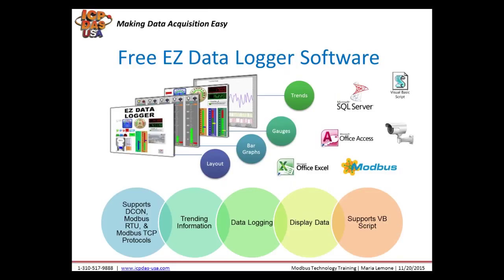Free Easy Data Logger is a software that we provide for use with our data acquisition equipment. You can use it with other vendors' Modbus devices as long as you have one of our ICPDAS devices in the network. It supports up to 64 I/O tags, which are words tied to memory locations in the computer that represent the input and output channels from data acquisition equipment.